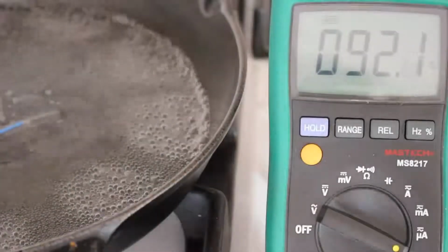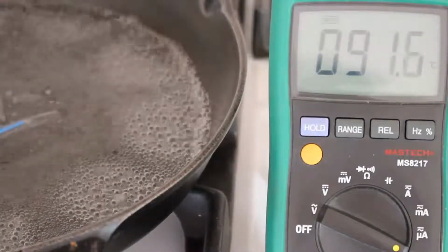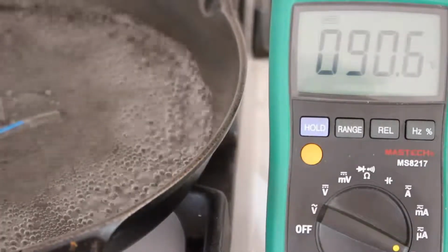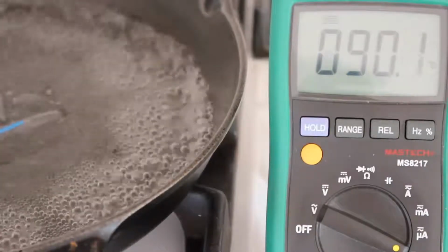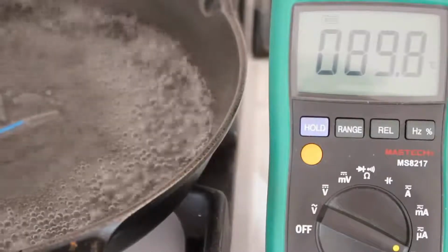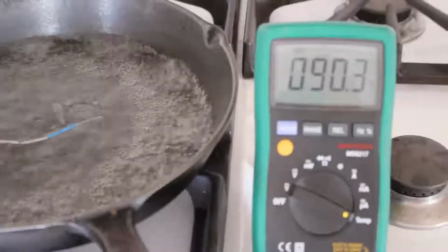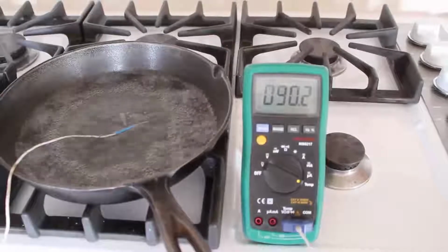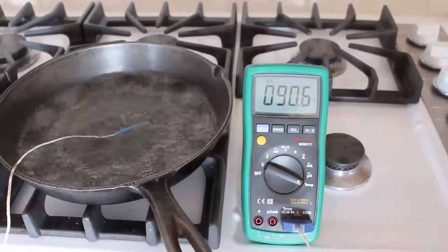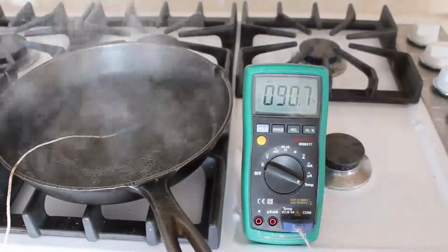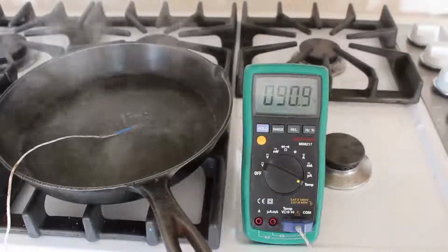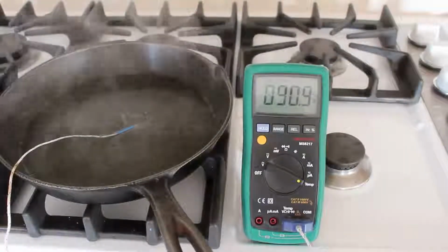As a final point, remember that our equation assumed that the pan properties were lumped. We assumed that the pan had a uniform temperature T sub B. However, if you were watching the demonstration closely, that was pretty obviously not true. The water around the edge of the pan was boiling and the water at the center of the pan wasn't. This implies that the outside edge of the pan is hotter than the center of the pan. So if the engineering question we have to answer is something like, what's the highest temperature that any point in the pan will experience, this lumped parameters model won't give us a useful answer.